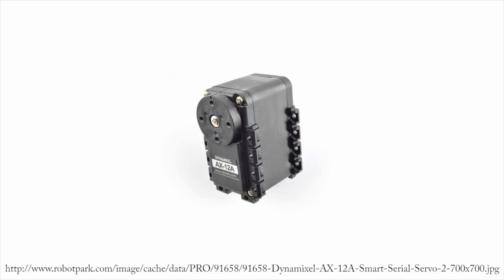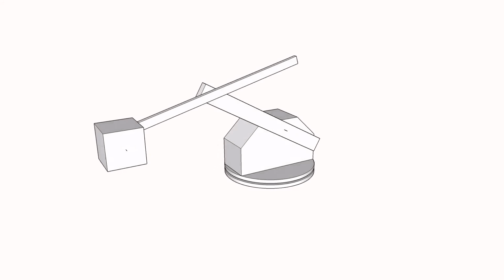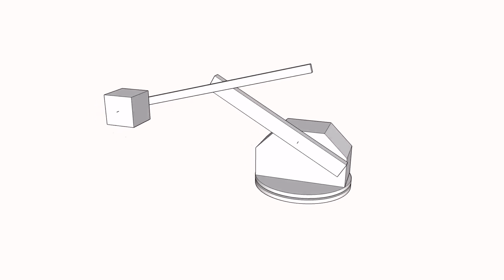I mean, they have continuous rotation if you want it. They're digital, position feedback. They can give you other things as well. They can be daisy chained. So order one of those. We'll give it a test drive. They're also pretty light, which would be a major advantage over the stepper motors for things that are further out, because you end up multiplying the mass by the time you get back to the final counterweight by 4 or 5.